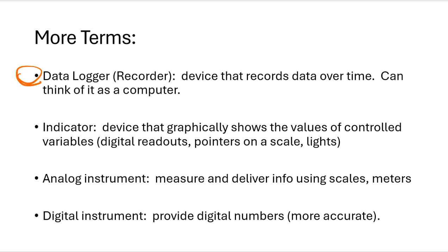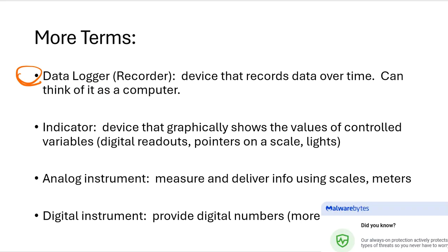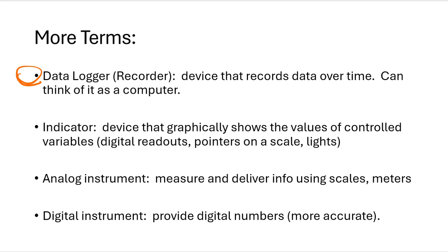So again, if I'm measuring temperature, then whatever that temperature readout is, we can have access to it 1 year, 2 years, 3 years later down the road. We can go back and pull up a date and a time and say, no, that vat that we fermented was at this temperature because my data logger told me that it was. So, a very important piece of the puzzle. And again, regulatory purposes love to see this type of information.